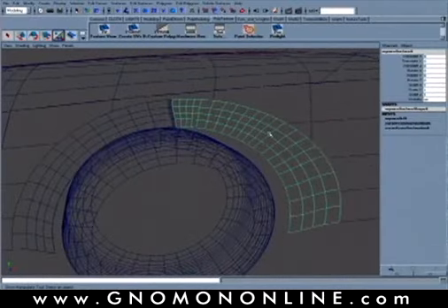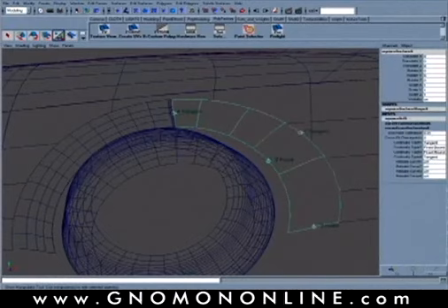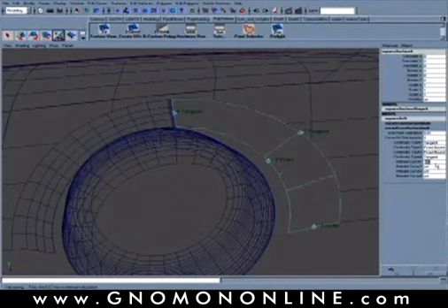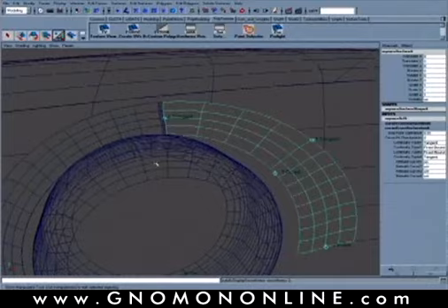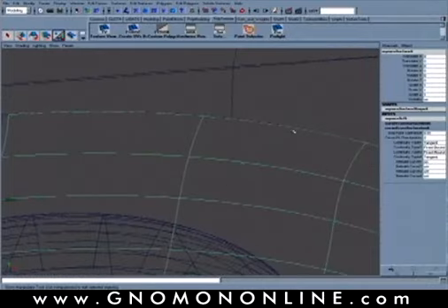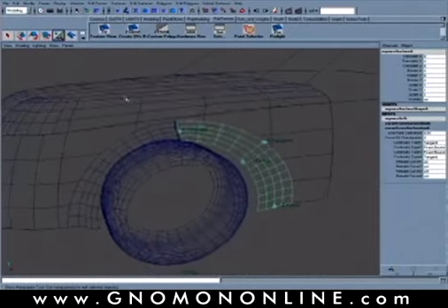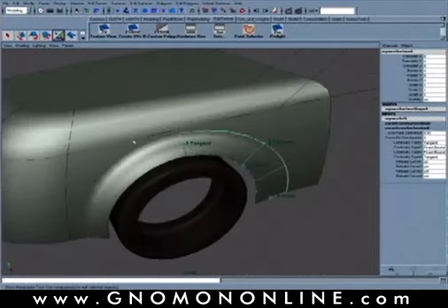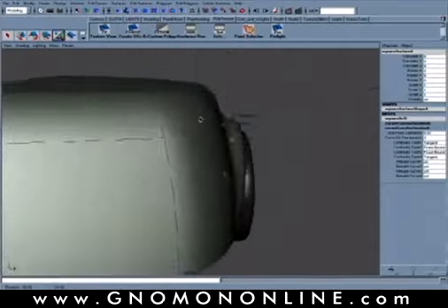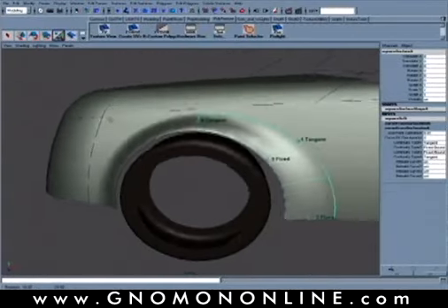Okay, this other surface we could also rebuild. So if I'm at level 1 and I go back to my square surface, I can see that is also edge number 1, and if I turn on rebuild, again you'll notice some data reduction. But this may have reduced it too much, which again is one of those things you want to watch out for. Is there going to be a noticeable gap in the wireframe between those two surfaces? So you have to use your judgment on that and see whether that is an optimal thing to do when you're selecting and rebuilding those surfaces.